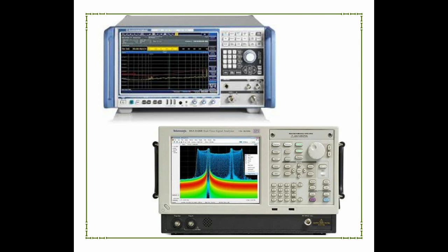Then EMI receivers are designed to comply with the detailed equipment requirements of measurement standards for RFI, such as the civilian specification CISPR 16-1-1 or the military specification MIL-STD-461. The EMI receiver has defined IF bandwidths, typically 20 Hz, 9 kHz, 120 kHz and 1 MHz. Usually spectrum analyzers don't have all of these and the standardized detector modes: peak, quasi-peak and average.